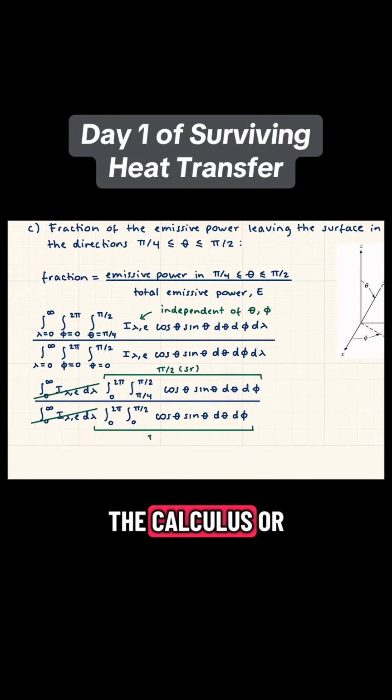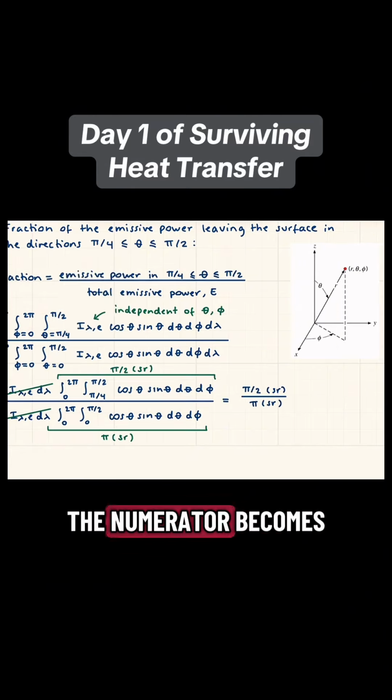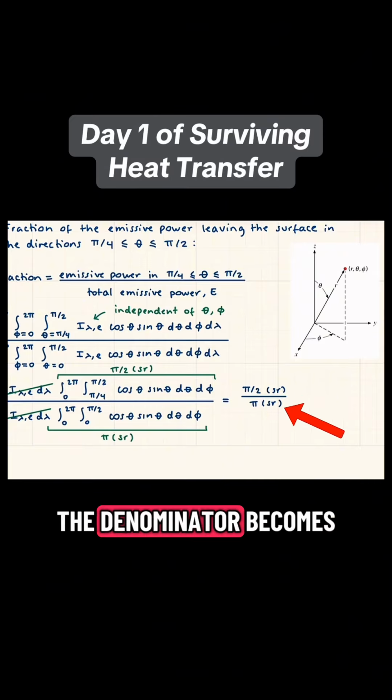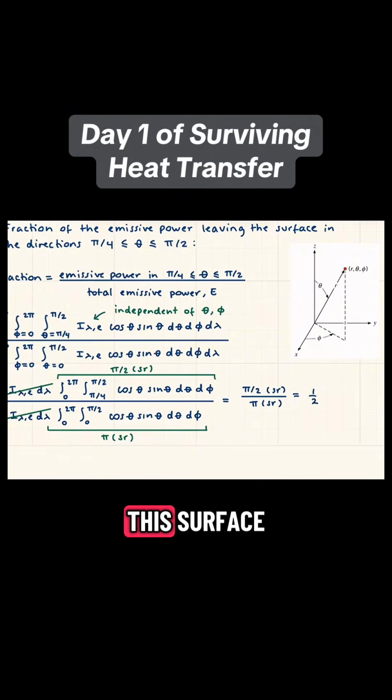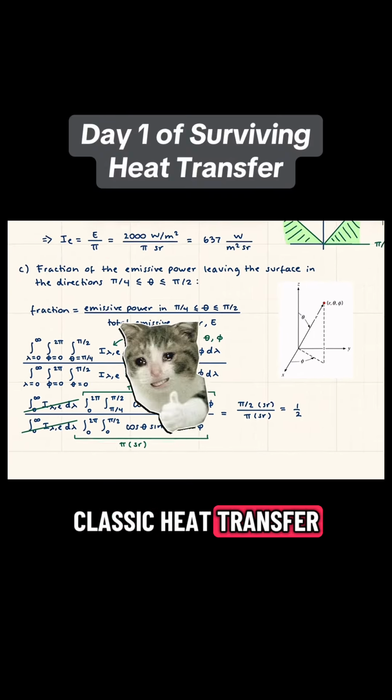And after doing the calculus, or skipping the suffering like I'm doing, the numerator becomes pi over 2. The denominator becomes pi. And the final answer is exactly 1/2. Half of all emitted power from this surface leaves between 45 degrees and 90 degrees from the normal. Classic heat transfer exam material.